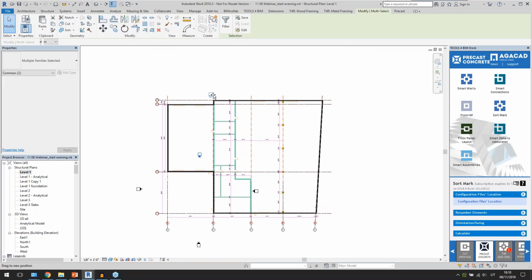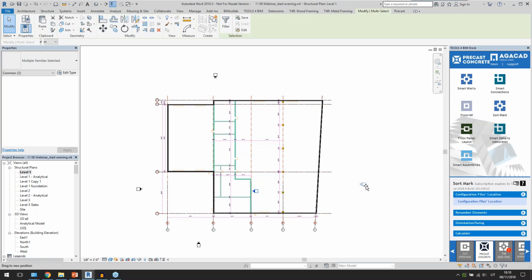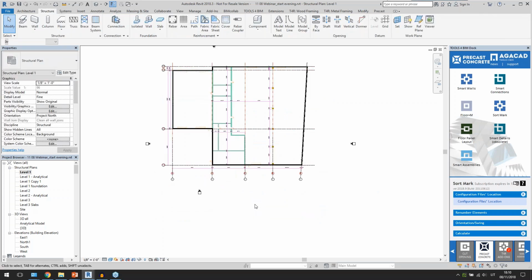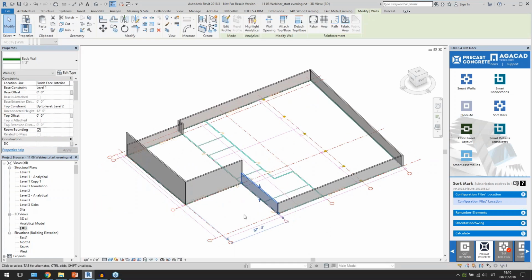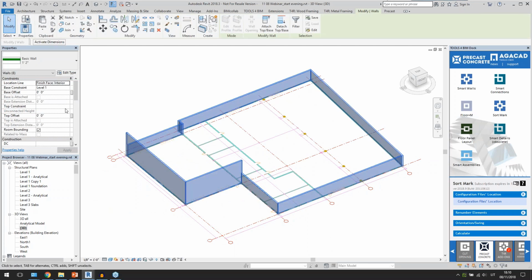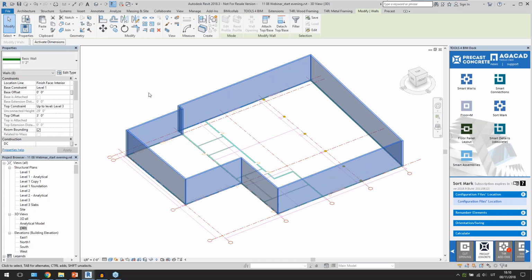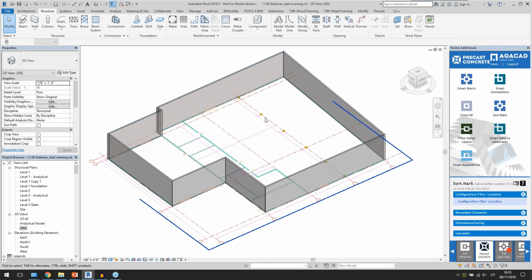So I'm just building big walls like this. These elevation marks, I can move them, so in elevation views I could get better views. All right, how does it look now? So I have walls, right? I forgot to change the size of it. It's not a problem in Revit. You can select them, select the top constraint again, and if you want to, you can add some extension even, right, like this. But then again, you have to go to sections, you have to see other DWGs or attach other DWGs.